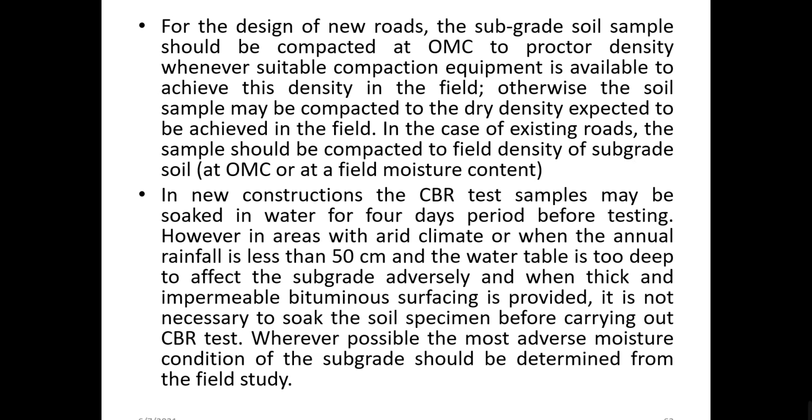For any type of soil subgrade, during the time of compaction, they have to lay the water before the compaction process is carried out. They have to lay the water through the tanker. Have you not seen the water being laid upon the soil subgrade before the compaction?